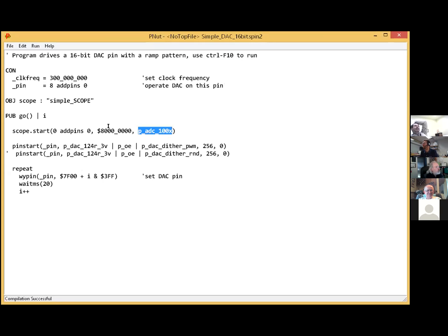We're going to observe the DAC climbing between, remember, it's just an 8-bit DAC. It can't output any fractional value, but by dithering in time, it can average out to really anything that's sub-bit. We want to look at it magnified, and we're going to output something right near the midpoint, and go up 3FF. If you add 7F00 to 3FF, you get 82FF. So we're going to go from 7F00 to 82FF.